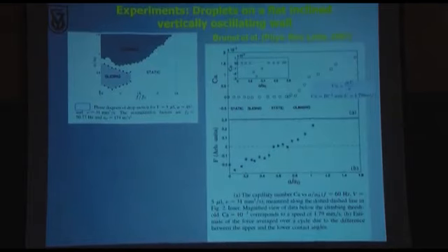What can we look at more here? For example, the capillary number, which is the cousin of our inverse capillary number, which we used in the previous part. The capillary number is shown here. It's mu times u, the typical velocity, divided by the surface tension. So if surface tension is fixed and mu is fixed, the faster is u, the larger is the capillary number.